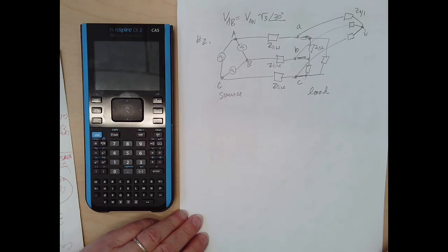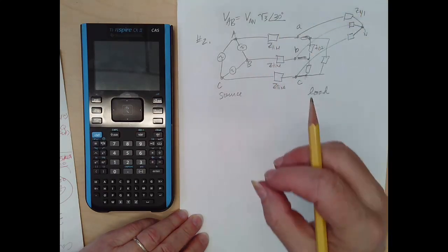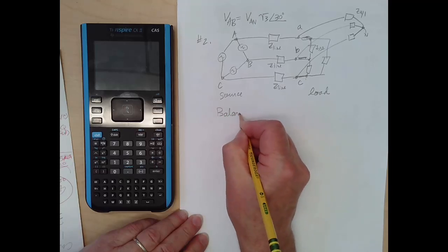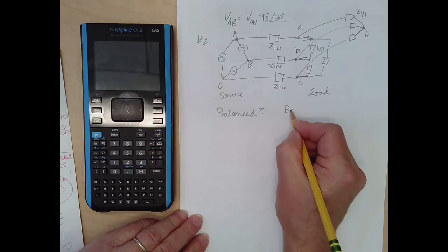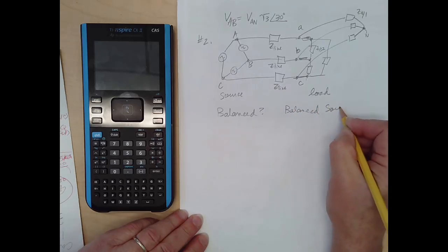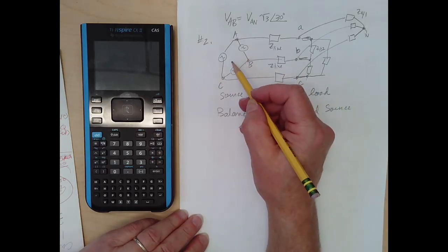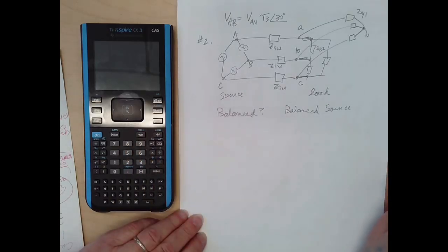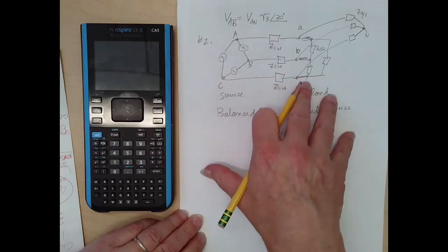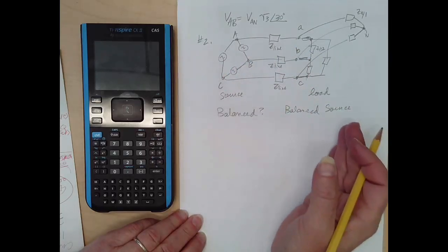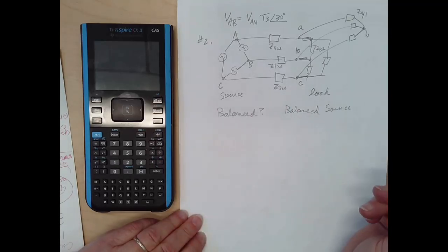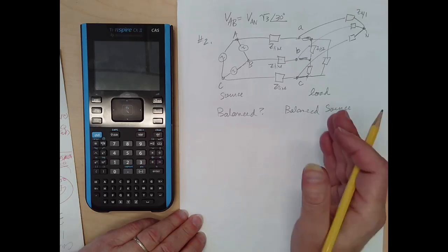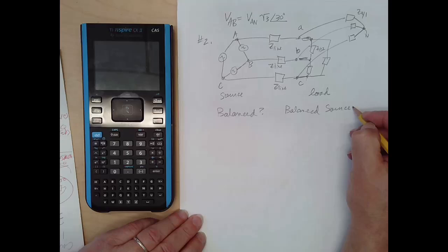All right. So first, we like to have balanced systems, because if we have a balanced system, we can convert everything into Y's, and we can draw what we call a one-line diagram. So is the system balanced? To be balanced, we have to have a balanced source. And usually that's a good assumption, because we have a three-phase generator. It's a three-phase machine. All three of these windings are wound on the same big core, and it rotates. They rotate together. And so hopefully they are very well connected, and so they will always be balanced. The machine is made so that when the A phase comes by, the B phase comes by 120 degrees later, so physically they are separated coils that cause it electrically to be 120 degrees out of phase. All right, so we have a balanced source.